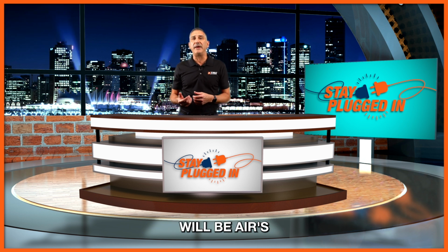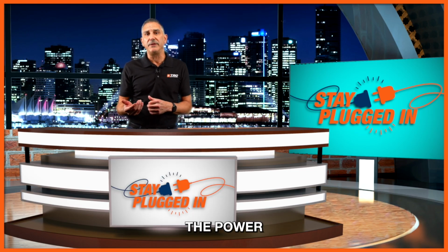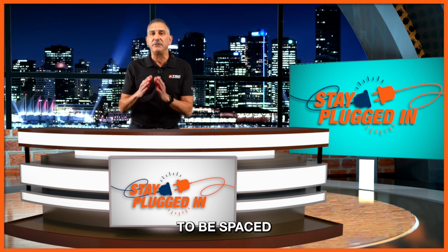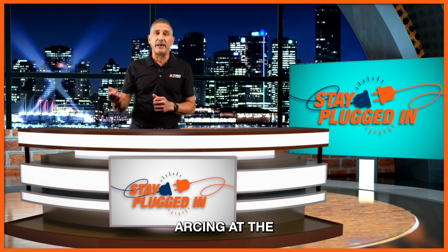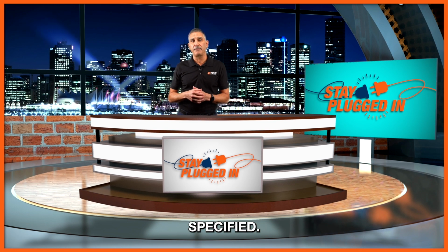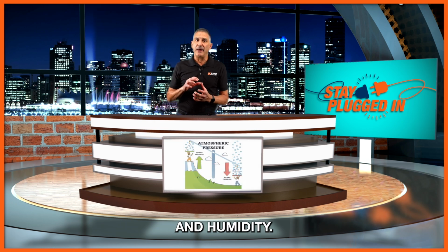Another effect will be air's electrical insulation. The air is thinner, which means that it also provides less electrical insulation. This can be an issue because the risk of arcing and electrical discharge increases with altitude. Now, components within the power supply may also need to be spaced further apart or otherwise designed to prevent arcing at the altitude specified.